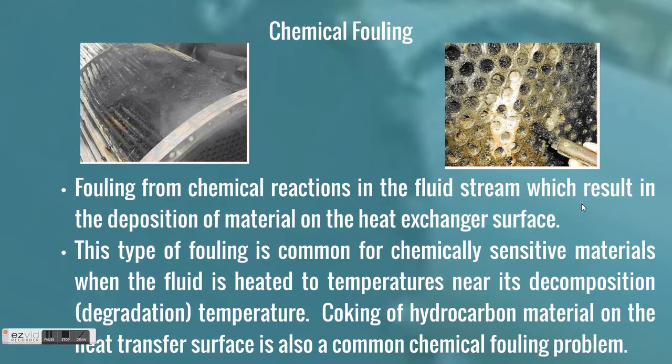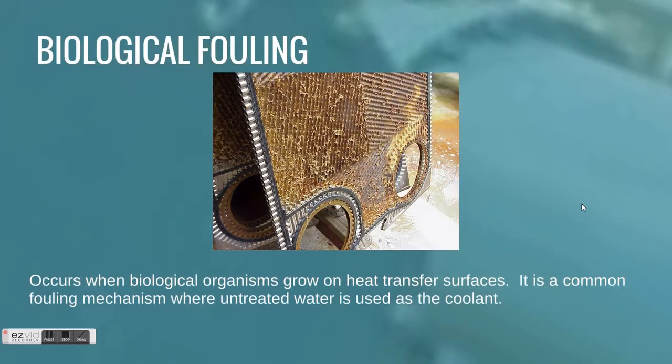This can be seen in a boiler or kettle, caused by the hardening of salt deposits onto heating elements. When the salt solubility reduces, it can cause an overall increase in the temperature. This type of fouling can be minimized by maintaining careful control over the temperature of the tube wall that is in contact with the fluid. Once it occurs, this type of fouling can only be removed by mechanical descaling or chemical treatment processes.